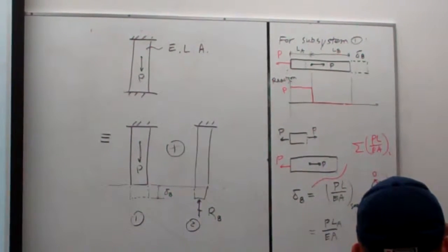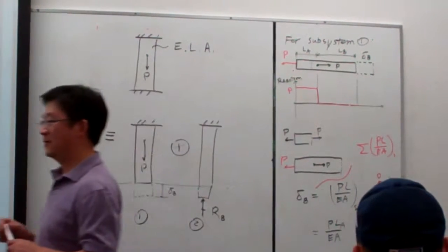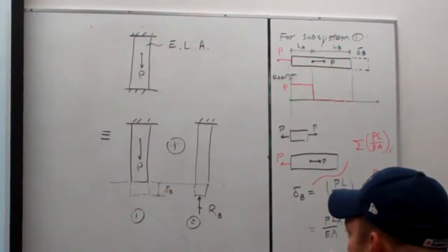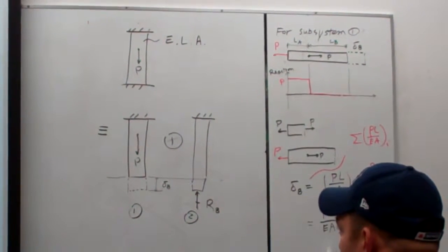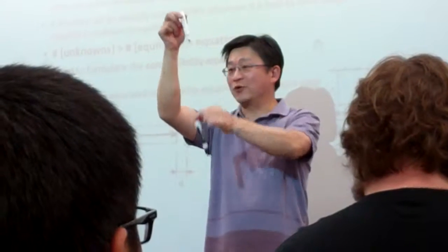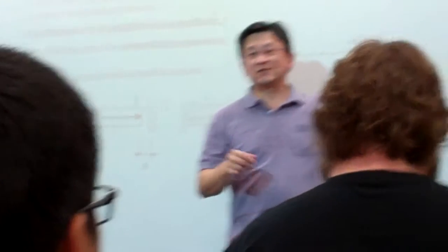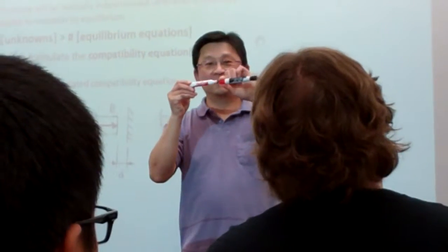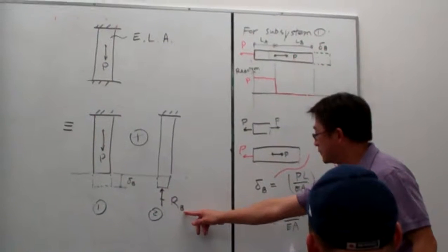You have to imagine if there's a really long rope and you're hanging from the middle of the rope, there's going to be tension on the top of the rope, but there isn't any tension on the bottom of the rope. Like this, I fix here, apply the loading here. So you can see this red portion is under loading, but the lower portion, our second segment, has no loading, right? Can you feel it? That is exactly this situation. Okay, so that is the first case, and now from here we can solve for the problems.